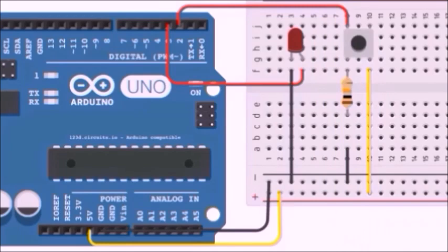Let's see the result. The LED is on, and when we push the button, it goes right back off. We got a pull-up with a pull-down connection. And if we go back on with a pull-up connection, yet keeping the same code, the LED is off, and when we push the button, it lights on. We got here a pull down with a pull up connection, and voila!